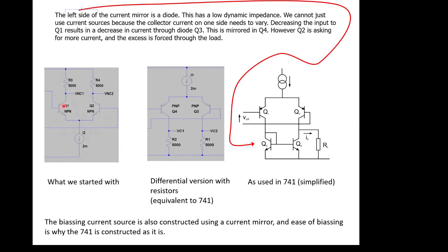What actually happens in the 741 is that it's inverted and is fundamentally driven by PNP transistors rather than NPNs. So think back, if we swap NPNs for PNPs, everything just gets inverted. So now we've got our bias source at the top. We've got our currents going through here, and then we've got an output reference to a negative supply rail. So it's just been flipped over. This is just what they did in the 741. It's just because that's what they had in those days. They had PNP transistors mainly.